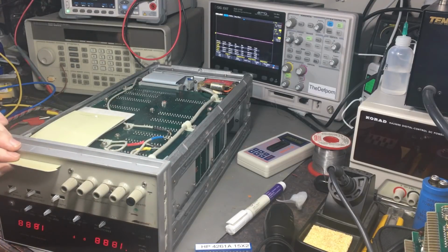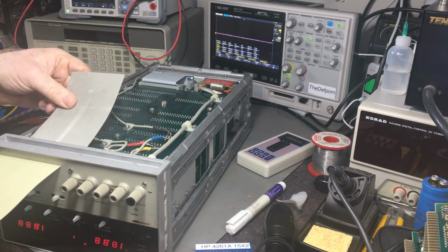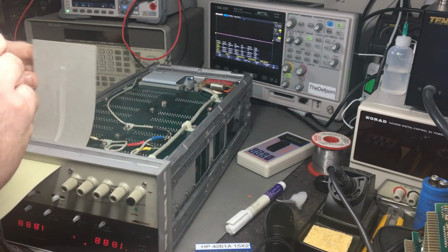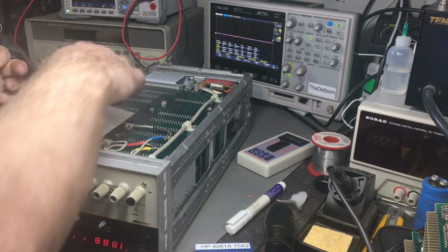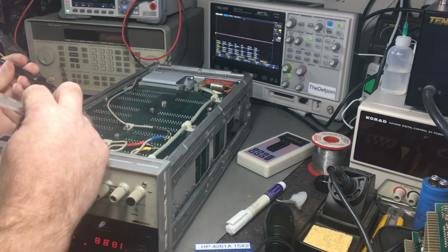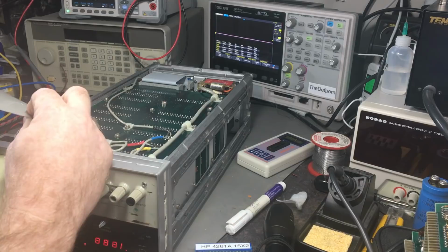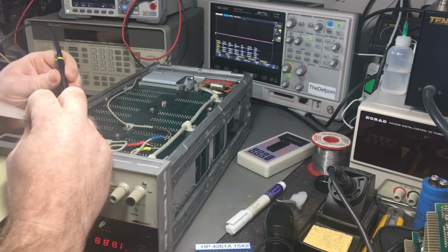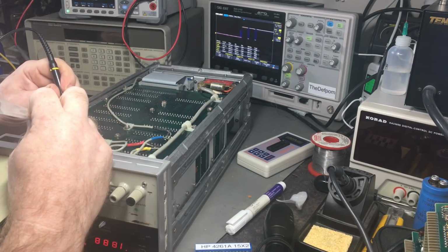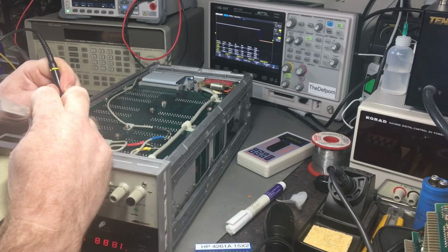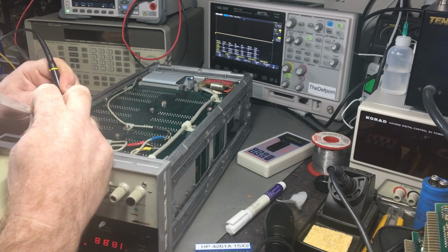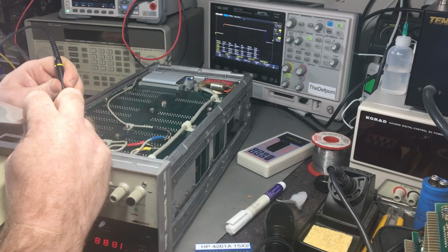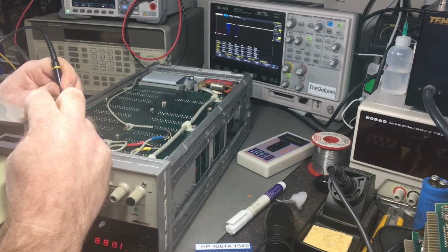So time to do the right hand section, which is under here, which is a bit awkward, but it is what it is. Be careful not to tear it off or something, because that'd be bad. Now, unfortunately you won't be able to see this. Now, what do I need first? First round is 3R, so third pin, right there. Well, as I count it up, it's pulsing, so yeah, that's pulsing fine. So I want 5R, which is that one there, which is marked. It's currently high. Is it going to change?